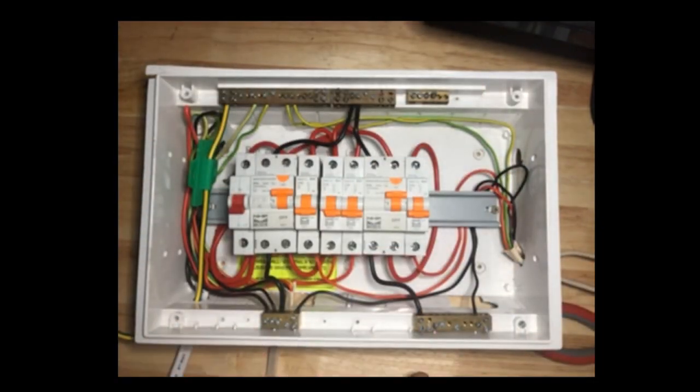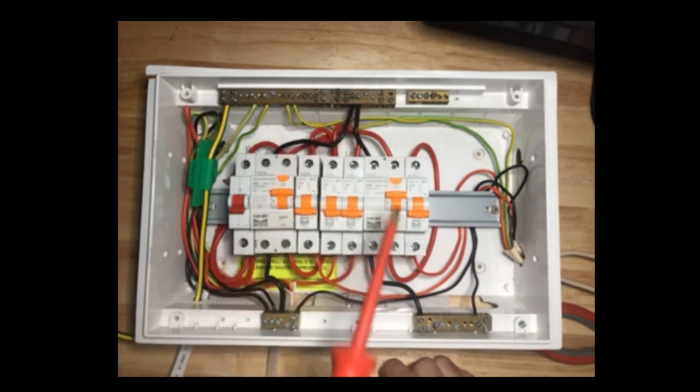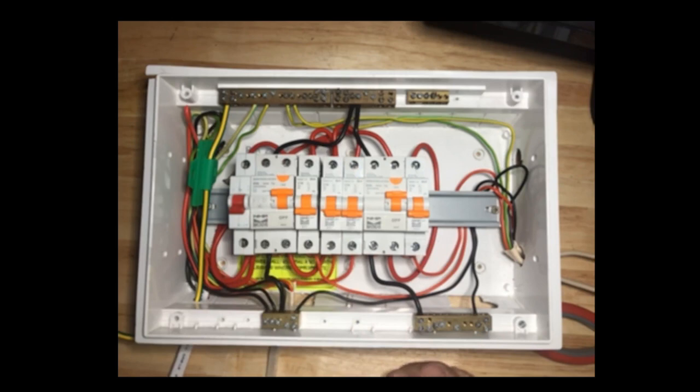Also worth pointing out at this point that this test must be done before the installation is connected to power. Once I've connected the installation to the mains, I never ever want to take that link out. It must stay in at all times. I also cannot do a resistance test while there's live power on the installation. So if I'm building a new installation and commissioning it, I must carry out this insulation resistance test first before I connect any power to my installation.